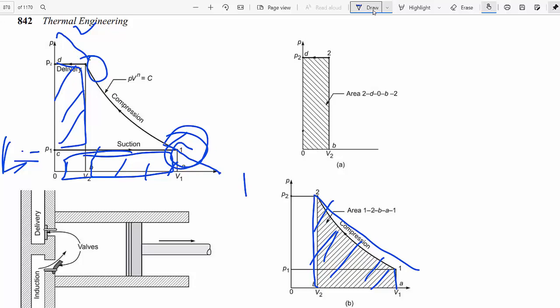Okay, a certain volume is there because it is the occupied volume of compressed air. Then the exhaust valve is open and compressed air escapes from the cylinder, at the lowest cylinder volume, to the tank. Then the volume is gradually decreasing and it matches with the y-axis. At that point only the volume is equal to 0. Therefore, which is the reason for the deviation of points 1 and 2 from the x-axis and y-axis.